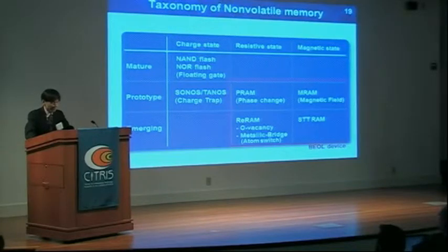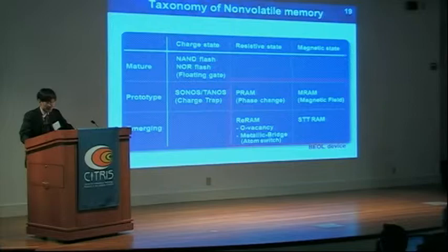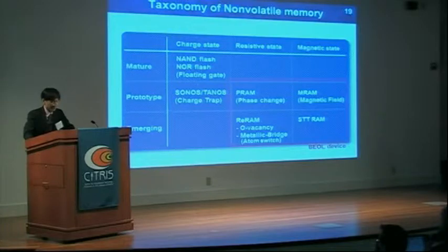Professor Philip Wong explained our memory type is the CBRAM. The other type of ReRAM uses oxide vacancy. And more importantly, this emerging memory can be formed in the backend. It needs a lower thermal budget. It has an importance for embedded memory application.